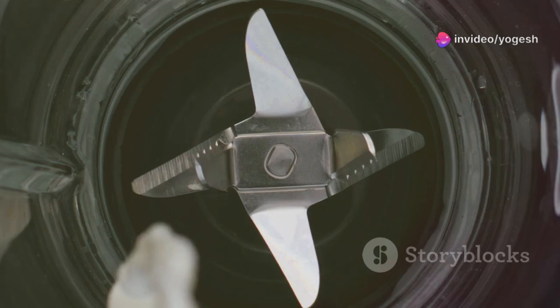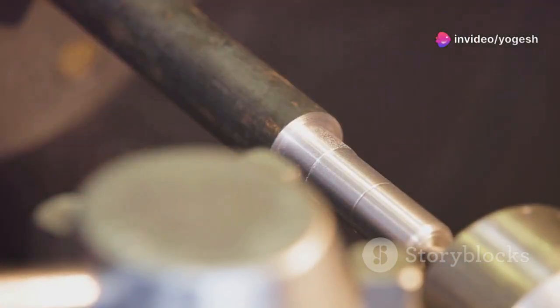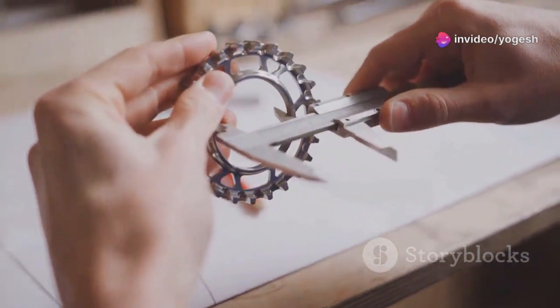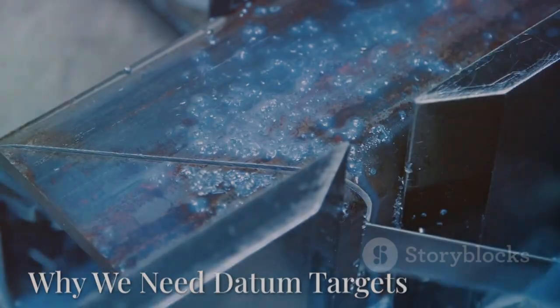On a drawing, a datum feature is a real surface or feature that establishes this reference. For example, a flat surface labeled as datum A becomes the basis for measurement when placed on an inspection plate. The key datums ensure parts are measured and assembled consistently, directly relating tolerances to real-world function. Smart datum selection is what makes a design robust and easy to inspect.